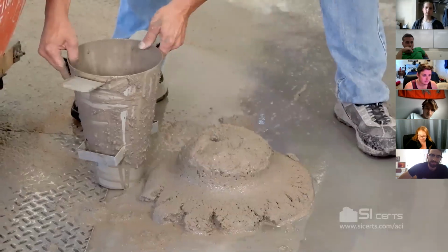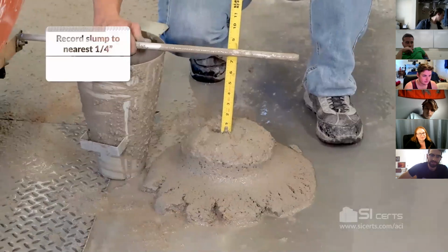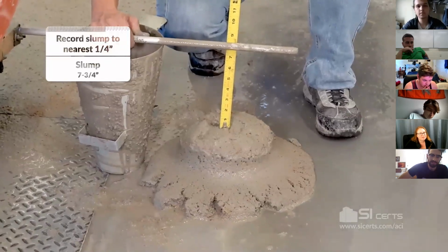We'll invert the cone. Measure down to the offset center and get your reading for your slump.